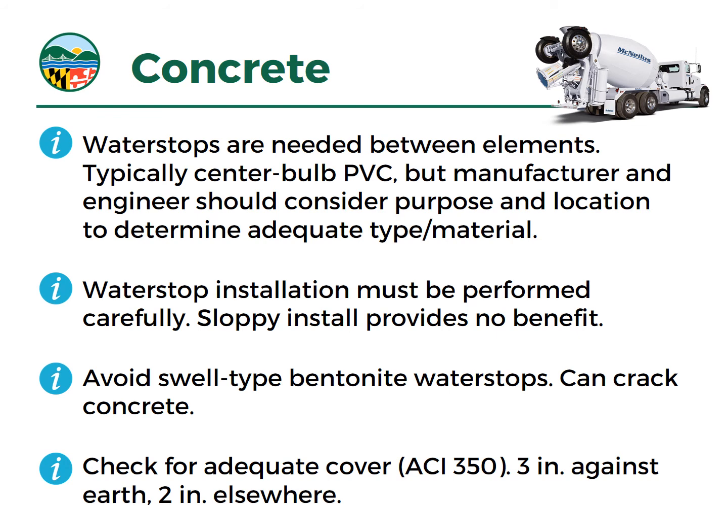We would typically avoid swell type bentonite water stops. They can work effectively, but if they're not installed properly or detailed properly, when they swell up, they can put some pretty high tension stresses in the concrete and cause cracks, and then they are ineffective. So water stop installation is something that needs to be performed carefully by experienced personnel. Sloppy water stops are as good as no water stops at all, and we want to avoid that.